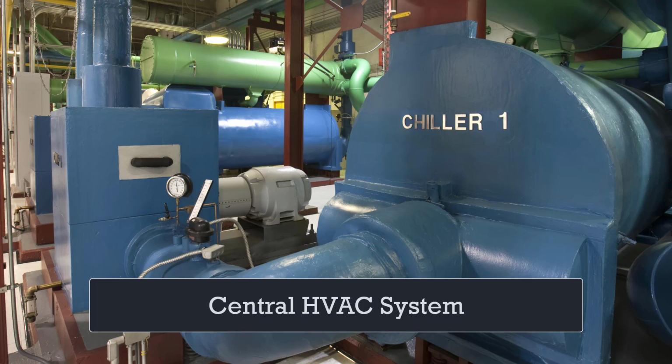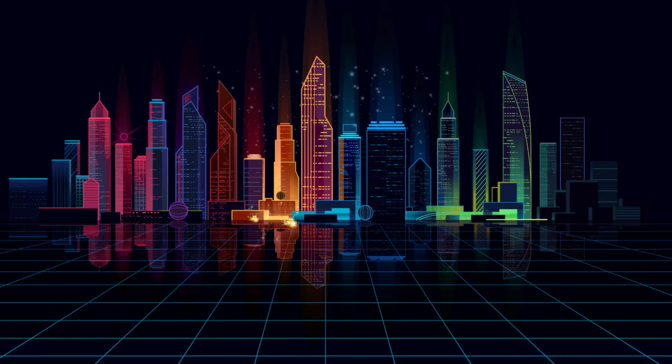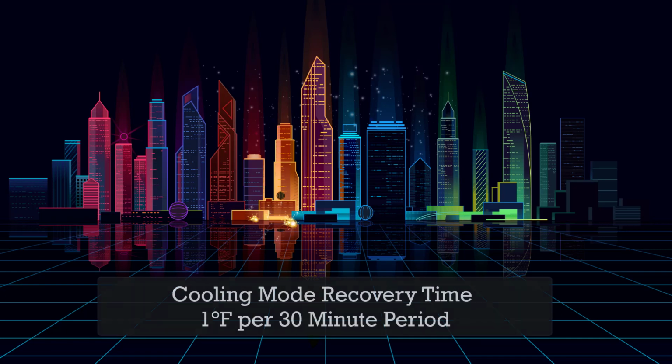Okay, at this point in the video, it's time for us to set up an optimum start schedule for cooling operation and then for heating. Let's assume our building is 200,000 square feet or greater with a central HVAC system. From experience, we can estimate a cooling operation recovery time of approximately 1 degree Fahrenheit per 30-minute period. In other words, prior to the occupancy period, when the central HVAC chiller plant starts, it should take an estimated 30 minutes to decrease indoor air temperature 1 degree Fahrenheit.